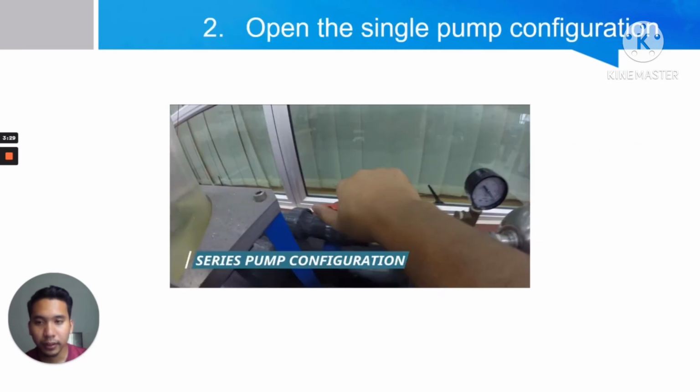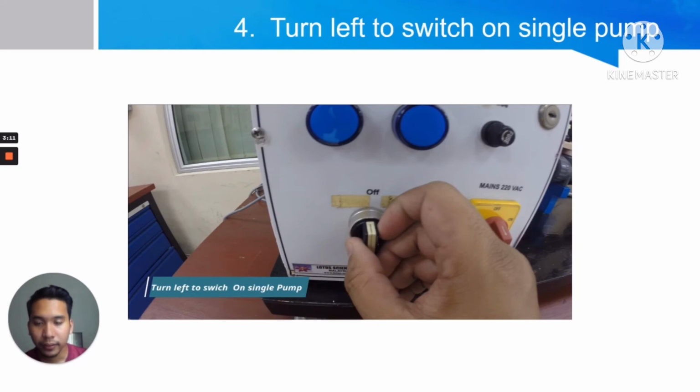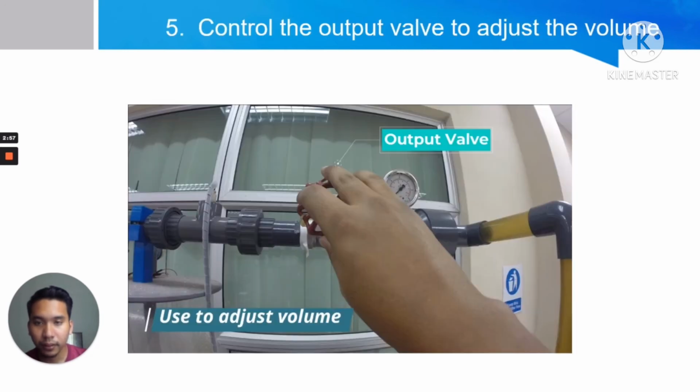So after we set up the apparatus, we need to test the single pump first. The third one is turn the valve to the right. As you can see in the picture, we need to turn right to close the valve. And for number 4, turn left to switch on the single pump. So we want to experiment with the single pump, so we need to turn left on the single pump. Number 5 is we need to control the output valve to adjust the volume.